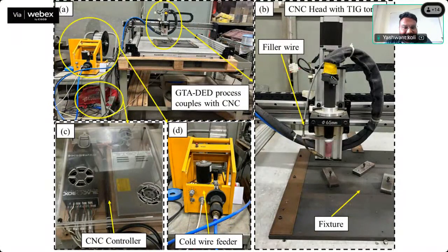So this we have integrated, that I've told you, that advanced TIG process, everyone is using this. Now Fronius has already made this advanced TIG into the market, and ESAB also, and Ador. These companies have already made it in this market. You can see here is the TIG torch. This is the standard TIG torch we are using. But what we have done, and this is low cost, you can see we have incorporated a small setup of this automated wire.